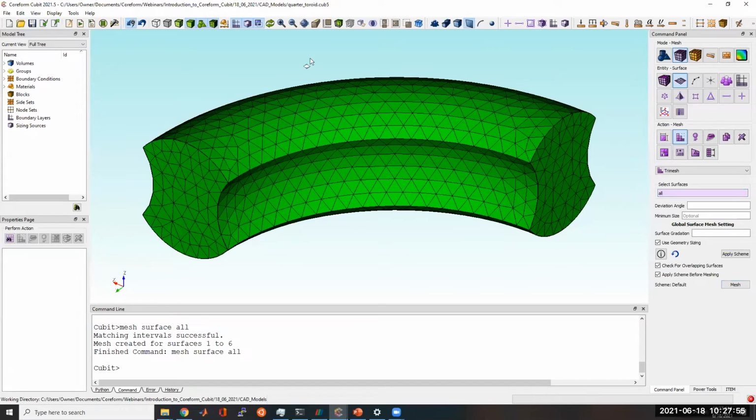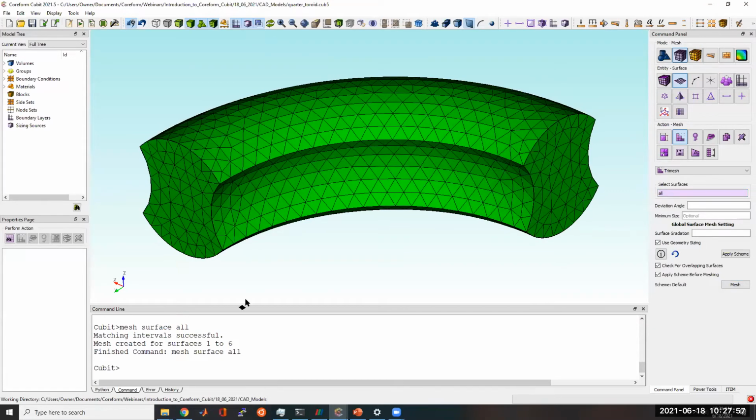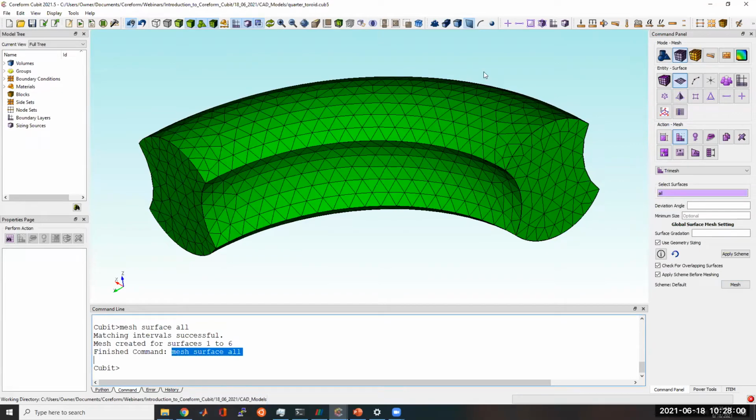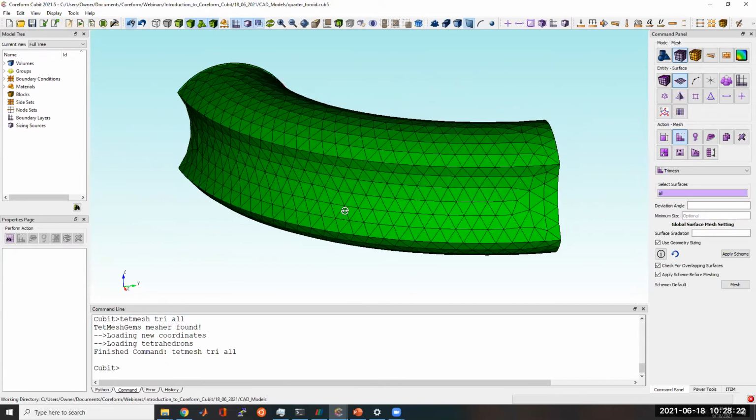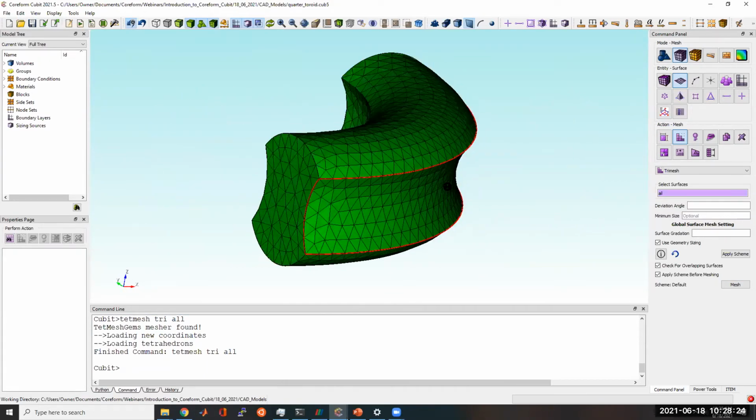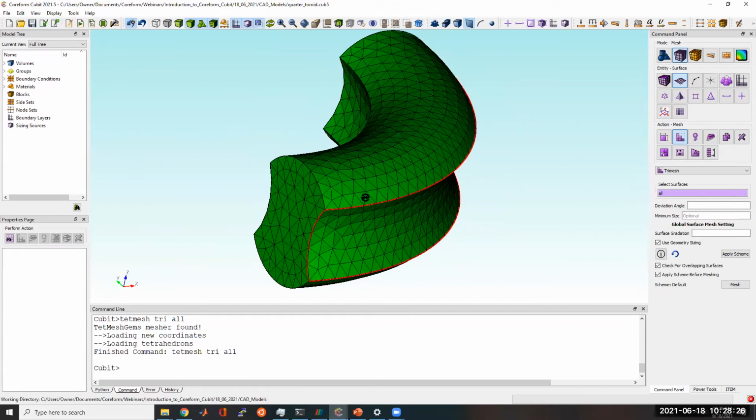And then from this triangle mesh, I've only meshed the surfaces here. There are no tetrahedra in this model yet. You can simply build a tet mesh from those triangles without having to update the triangulation. That's a solved problem for tetrahedral meshing. Just generate any valid triangle mesh, and you are guaranteed to be able to build a tetrahedral mesh.